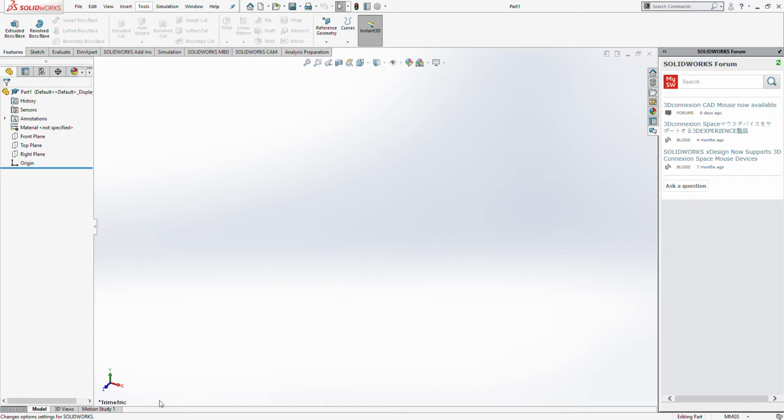And then perhaps the most important thing is if you look all the way down to the bottom, there's a Tools Options menu, and within that options, there's actually a document area where you can customize your unit system, whether that be metric or customary, and also edit your general SolidWorks documents and properties and settings. That'll be very helpful for you later on when you're wanting to work efficiently. It's a lot to look into, so we won't jump into that.